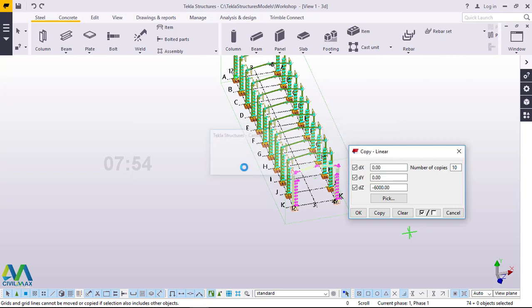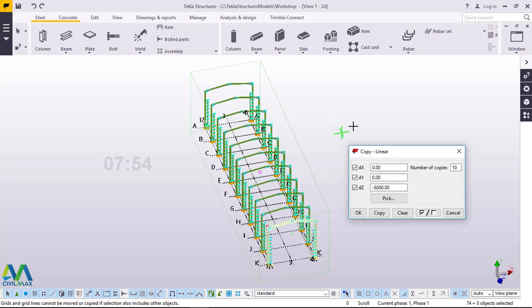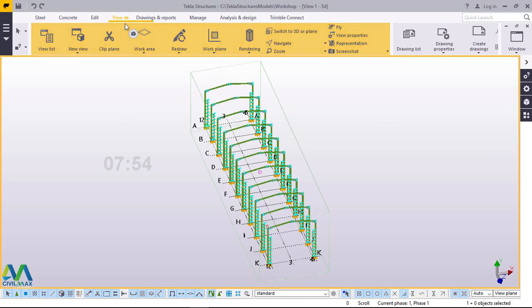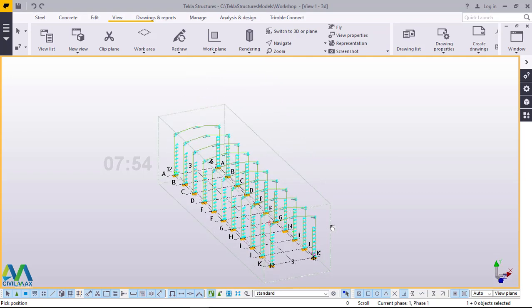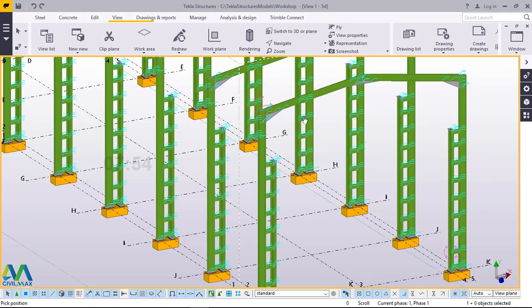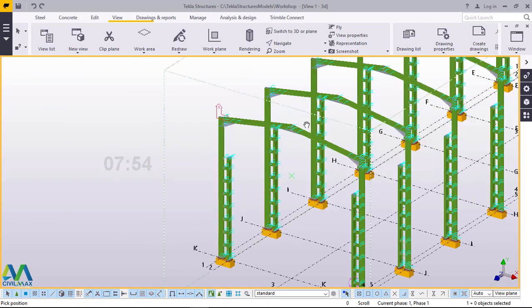We'll click expand just to allow space for any extra that we will delete later on. Right click and interrupt, click OK. We'll right click and come to view, or you can press Ctrl R, just press Ctrl R and pick the point of rotation. I'll pick that after pressing Ctrl R, and I'll be able to turn this round like this, and this will wind up our tutorial for today, and we'll be able to continue with the rest in the next presentation.